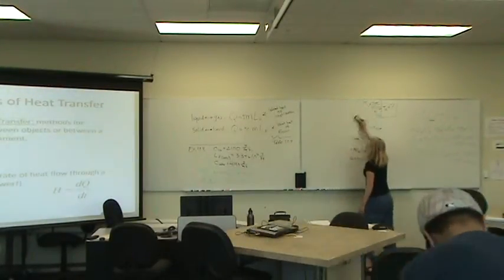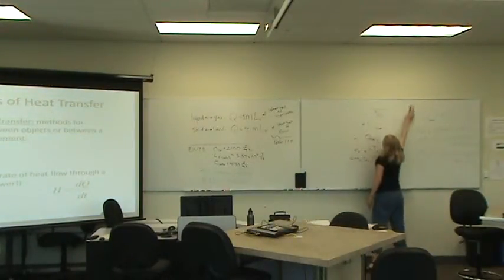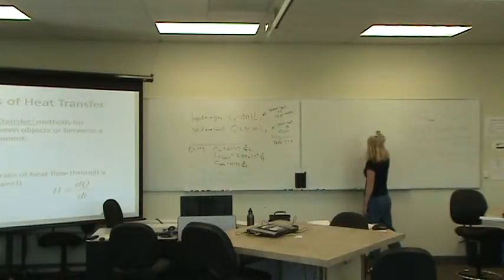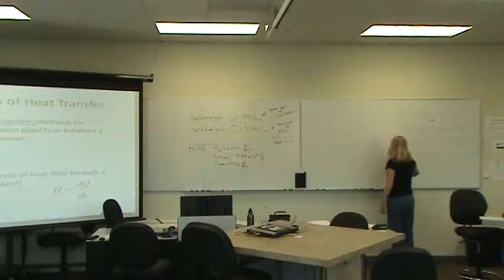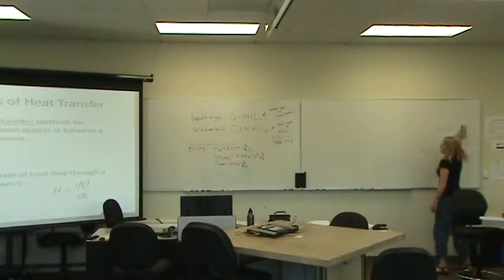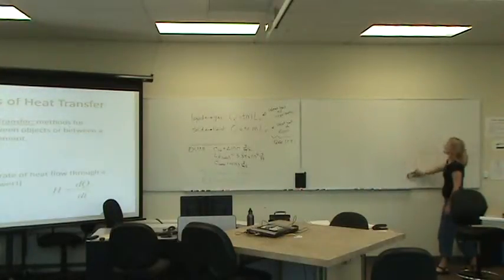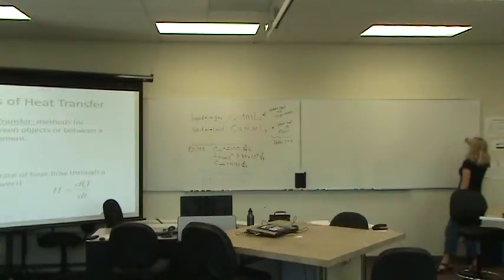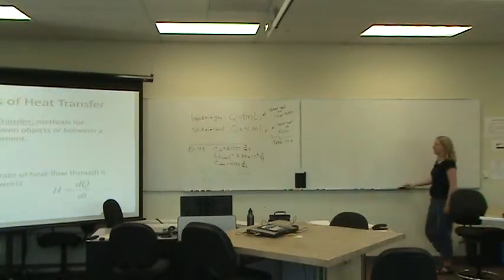Okay, so the last topic is mechanisms of heat transfer. And this is, as much as I'd like to skip this, pretty important for 3D printing. This is how heat transfers between objects. So there's a couple ways: conduction, radiation, and convection. Under radiation, you could also add absorption, but the process is the same whether you're radiating or absorbing heat.